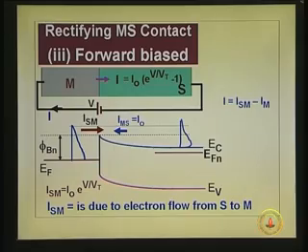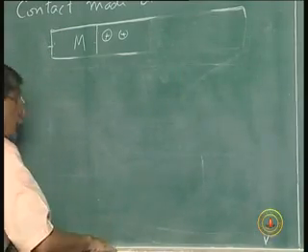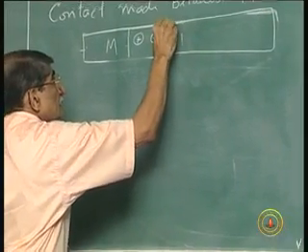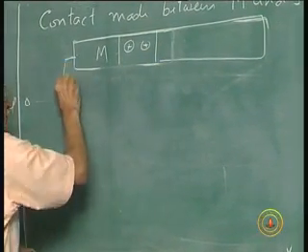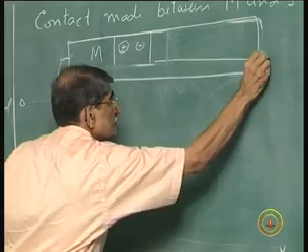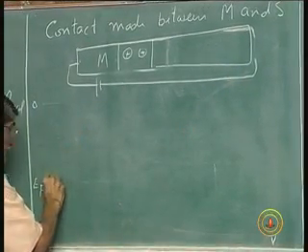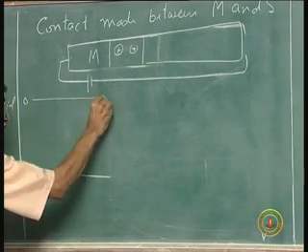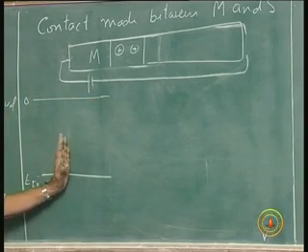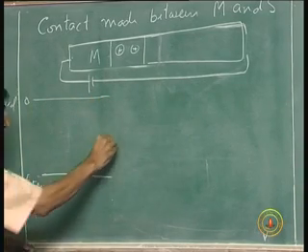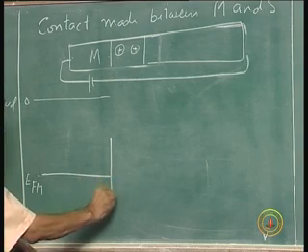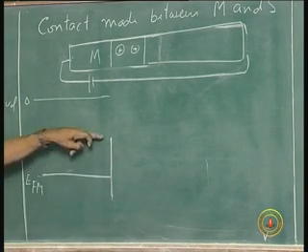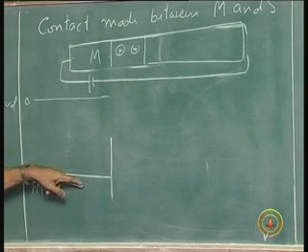Now, from the thermal equilibrium situation, we have reduced the voltage by applying a forward bias. In this situation, this has not changed, that level remains the same, because nothing is happening at that level. In fact, the barrier height doesn't change, because barrier height depends upon this conduction band edge and the Fermi level.